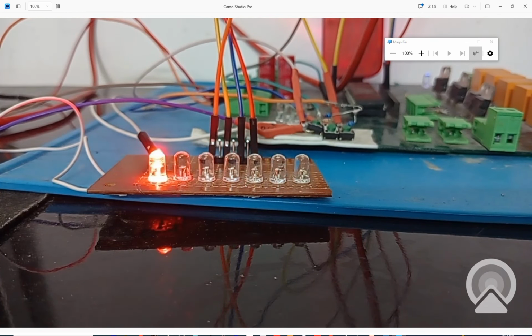So guys, that's how you can play with the bits in MikroC for PIC. You can use the bit shift operators to shift the bits either to the left or to the right. This technique is very useful, especially whenever you are receiving data from a single digital serial input pin, like a DHT22 or DHT11 sensor. Then you need to do this bit shifting because you will get the bits one by one, so you have to store them in a single variable. This is a very useful technique. You will find a lot of uses of it in your programming.